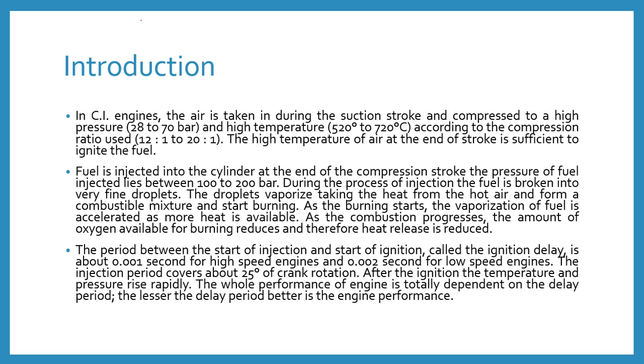So these temperatures are sufficient to ignite the fuel. The fuel is now injected into this compressed air with the help of a fuel pump and an injector. Every particle of the fuel injected into the engine cylinder gets enough oxygen from the compressed air, so there is complete combustion.